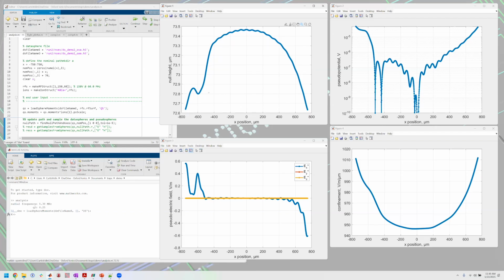The biggest morphological feature that's interesting here is this dip. This is maybe about 300 nanometers, so 0.3 microns. It's a pretty big dip. That is located over the load slot, and again, this is a very tiny load slot. You would certainly observe that kind of difference when calculating waveforms. You would see what looks like a stray field if you were using a gapless approximation and generating a waveform.